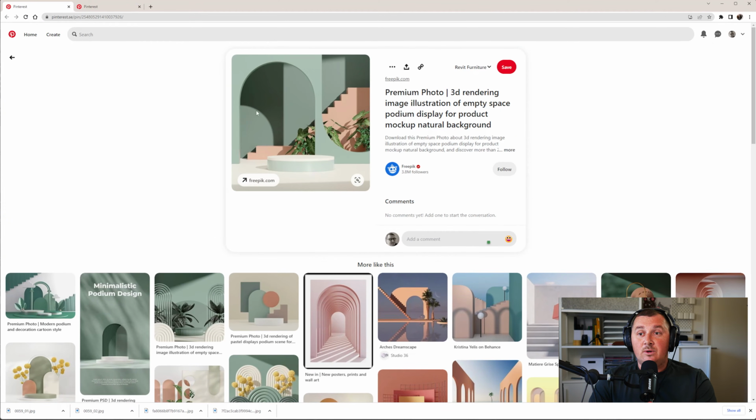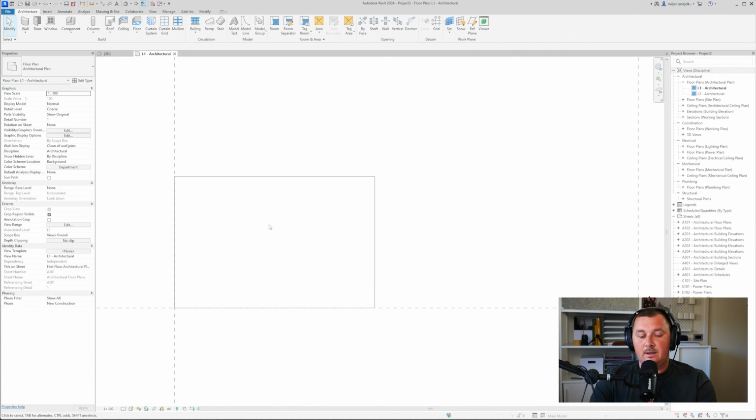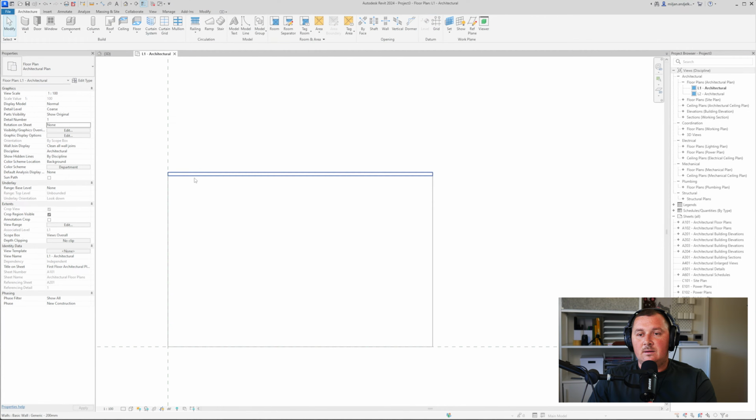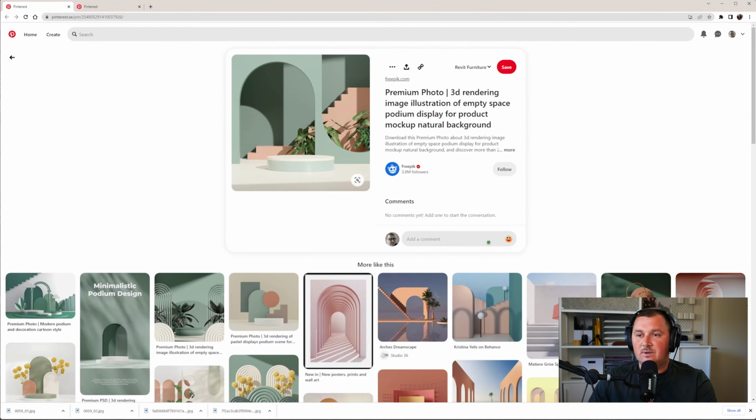So now I'm going to make this back wall. What I have in mind is, let's say, that the back wall will be here, and the camera position will be somewhere there. So I'm going to use a wall. We'll take exterior and I can make it, let's say, 8 meters. Then let me just take a picture again. So it has a green color, so it's different than the floor.